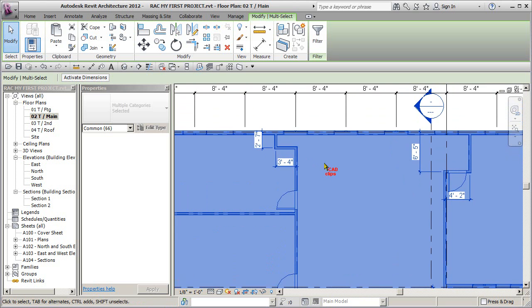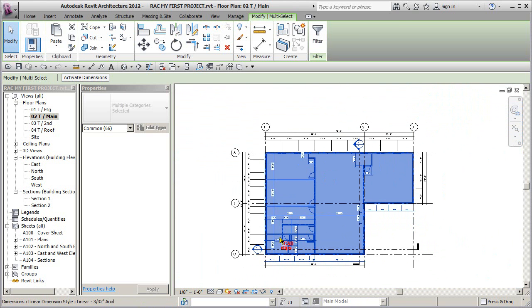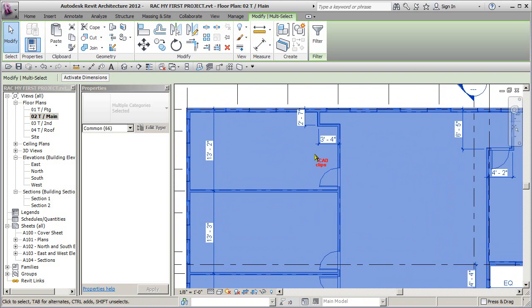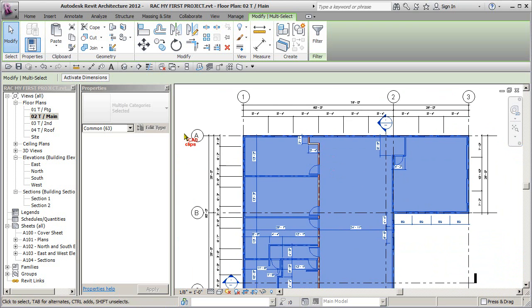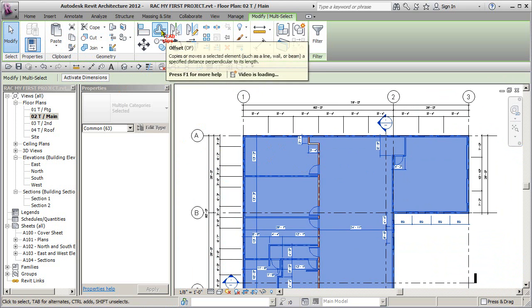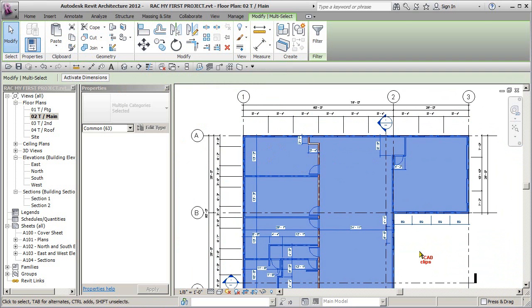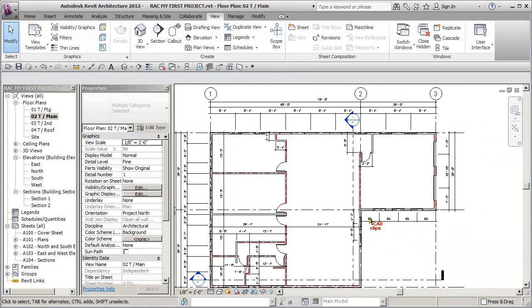So my hands aren't on anything right now. They were just selected, right? I just did a big window box and did my selection. Now I'm going to go down here, wheel in, hover over here, hit Tab first, then hold my Shift key in and make the selection. Now those have been deselected, and then I can either move them or copy and paste them or do whatever I want with them. I'm selecting them for a reason. Maybe I'm moving them, mirroring them, rotating, who knows what.